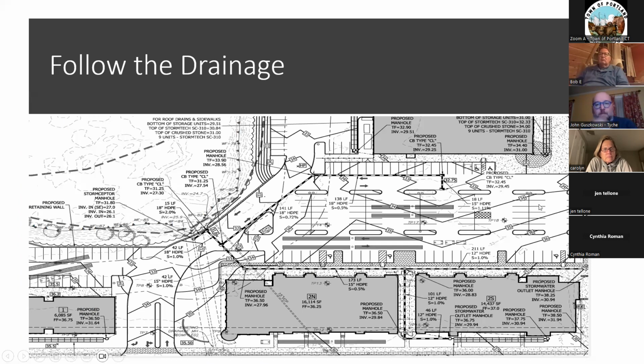All right, last little bit, we'll just talk a little bit about drainage, because this is kind of an important thing, particularly on the planning and zoning end. The drainage lines are shown in sort of black and white dashed lines. You see what I'm tracing here? There are drainage lines over here, drainage lines over here. And what we see is topographic lines. So we have the 33-foot contour here, 34-foot contour here, 35. So we're going slightly upslope as we go over to the west.